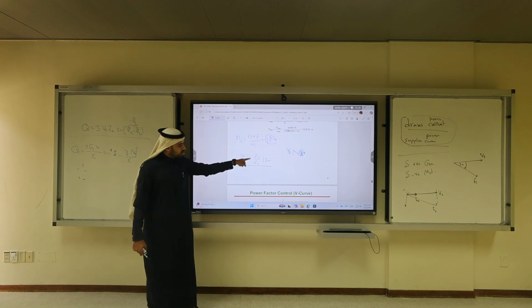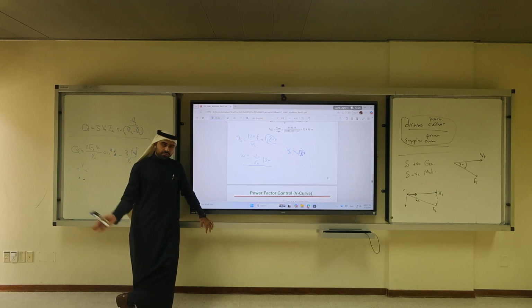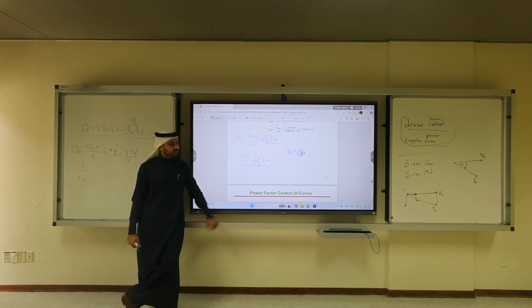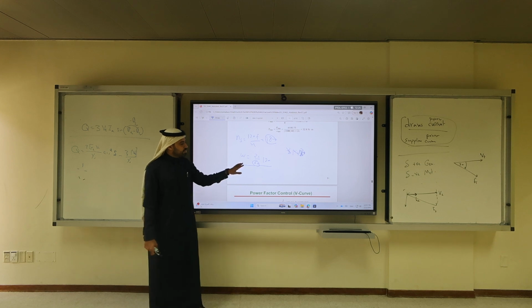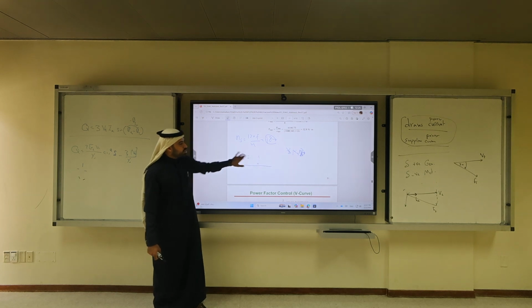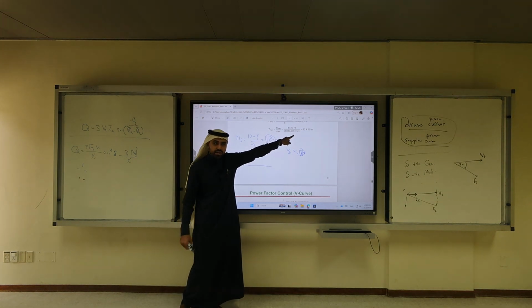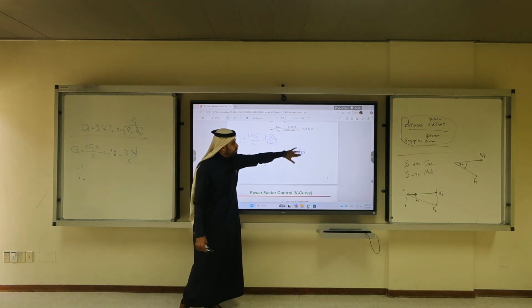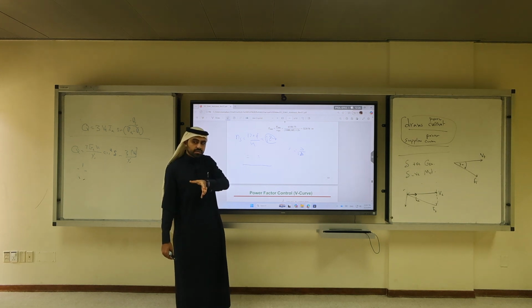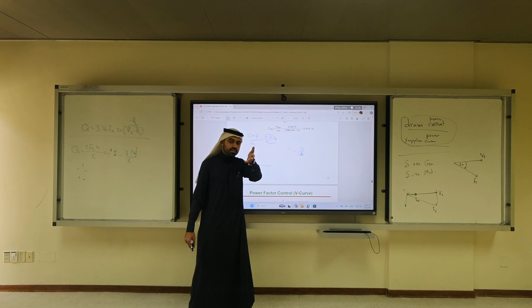This is how they define it. So this 2 pi and these numbers 60 come from the conversion from radian. So 60 because of what? Frequency. Yes. 60 minutes. This 60 is because of 60 seconds, not because of 60 hertz. A minute has 60 seconds. Basically, this 60 has nothing to do with the 60 hertz, okay? So even if you're at 50 hertz, this 60 would still be there. That's my point. And this 60 comes from a conversion from minute to second, radians per second to RPM, from RPM to radians per second.